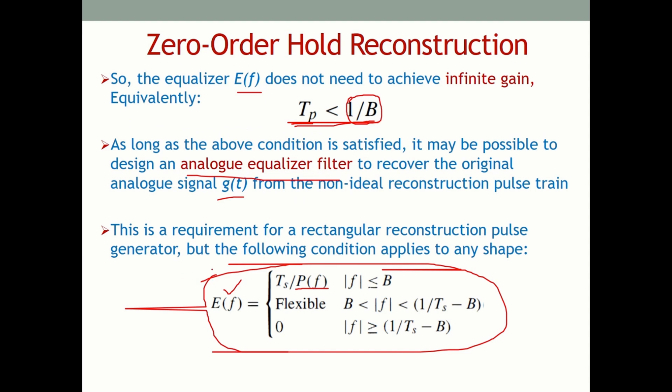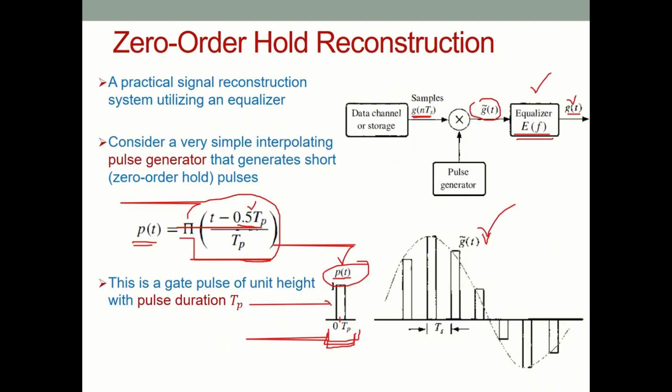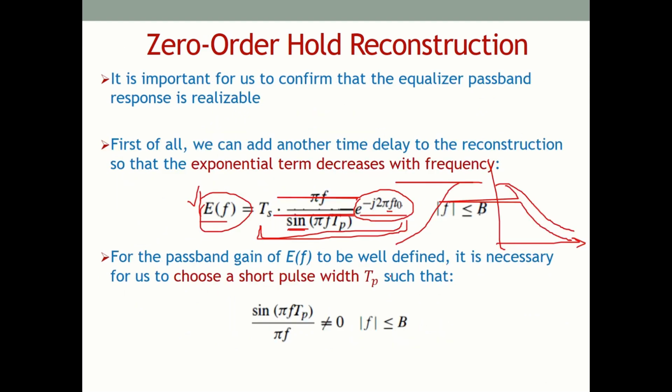This technique that we discussed here, where the pulse shape is rectangular, is called zero order hold filtering, because as you can see, if we sample here, the sample retains its value until the next sample is reached, or just before the next sample, when the width of the pulse is covered, right? So this completes the discussion on practical reconstruction of sampled signals.